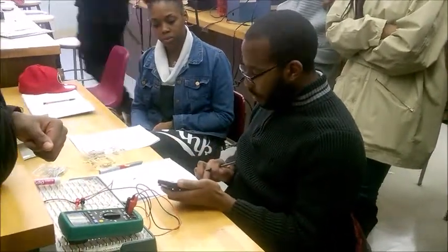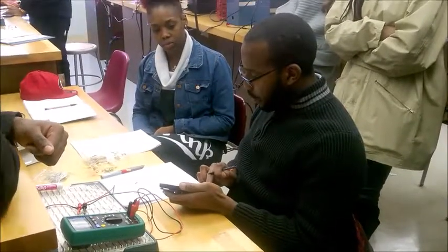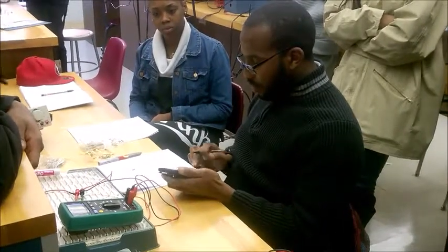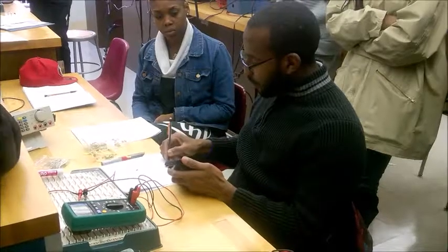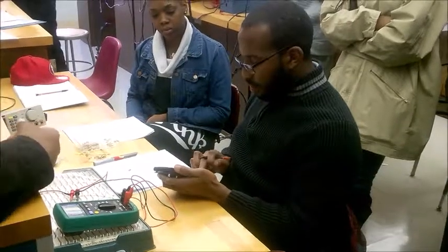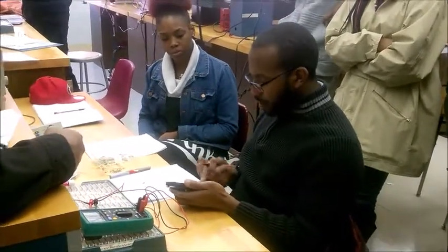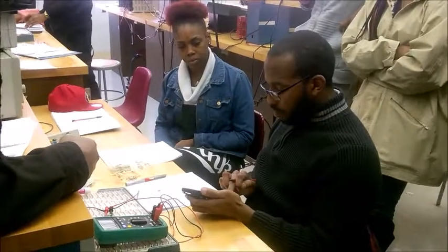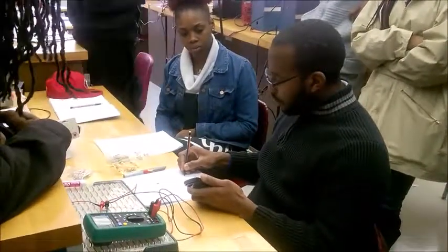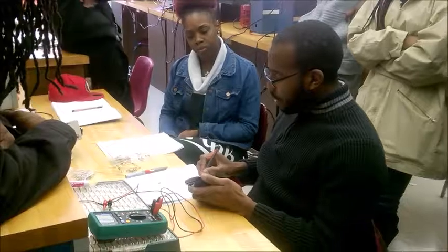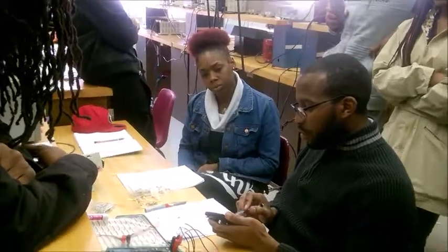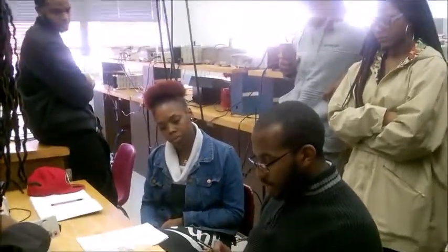3.09. Move here. 2.122 divided by the measured resistance 325.58 is going to give me 6.55 milliamps. Likewise here, 3.544 divided by the measured resistance, remember the resistance is fixed, 325.58. This is 10.8 milliamps. Again, this is in milliamps, it's in thousandths of an amp. So if you notice here, the 1 milliamp is here, 10 milliamps is there, 100 milliamps is there, 1 amp is right here.